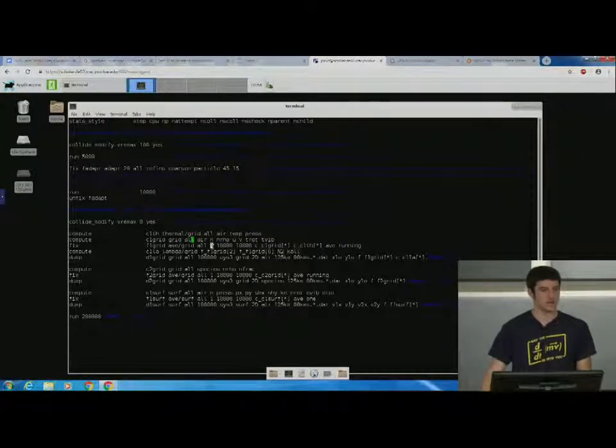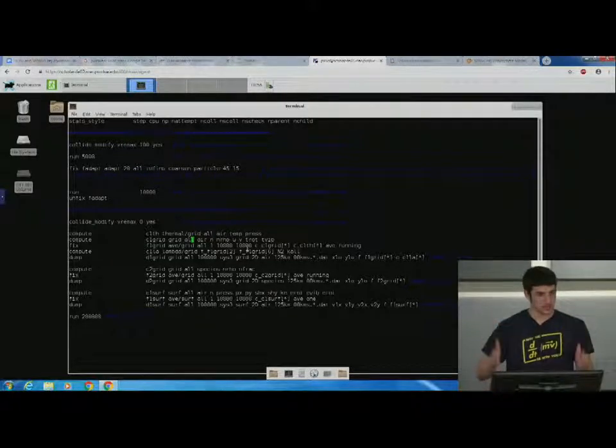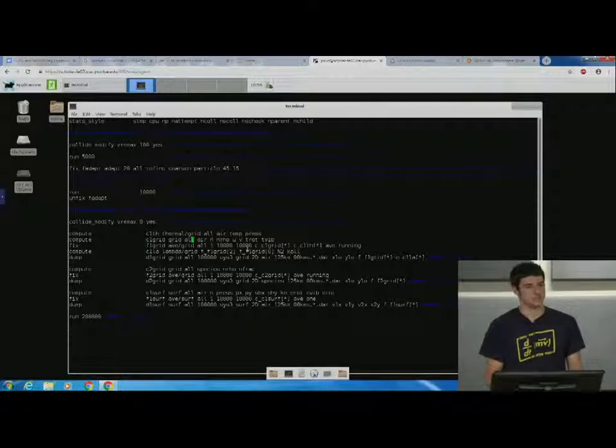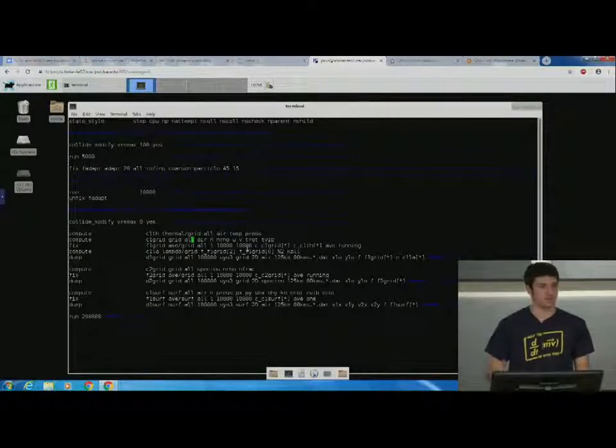So one step. The example that they give for these numbers would be 10, 100, 1,000. If it was that, it would be every 1,000 steps I'm going to repeat my fix command. For 1,000 steps, I have the last 100 steps. And for the last 100 steps, basically for step number 901 to 1,000, I'm repeating the frequency every 10 steps. So it'll be 901, 911, 921, and on until I get to, or maybe it starts at 900, whichever way it starts. But it continues that.